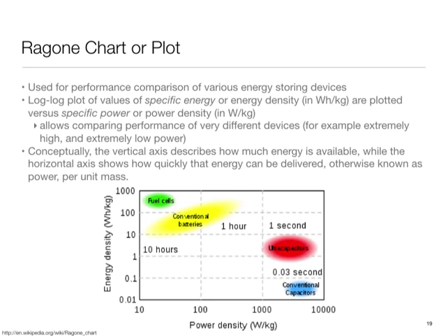Capacitors do have some other disadvantages. Capacitors can supply a lot of power, and in the reverse also, they can suck in a lot of power very rapidly, so you can charge them very rapidly. There have been some efforts on putting a capacitor along with a battery in your phone so that I can charge it rapidly, so you get an initial sufficient charge while your battery then charges up. A capacitor disadvantage is it leaks more, unless you do some stuff, and capacitors also age. So there are cons also. But this plot was an attempt to show that.